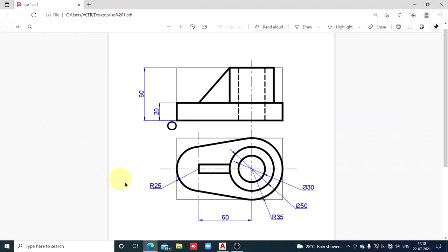So in this orientation you are going to measure width in isometric view. Horizontal dimensions in the top view or in the front view, those dimensions are parallel to length axis, and parallel to length dimensions you are going to measure in this orientation. Width, length and height. So left axis is width because point O is on the left side. So length 120, height 60, width 70 in millimeters, of course. So now this will give you rough idea about how much space is required to draw this drawing.